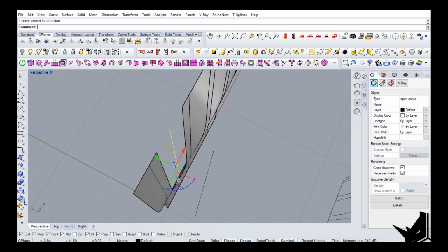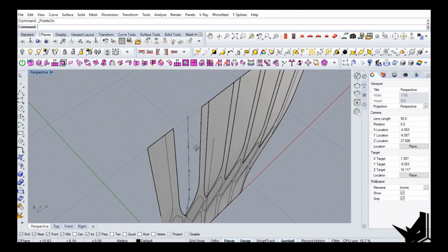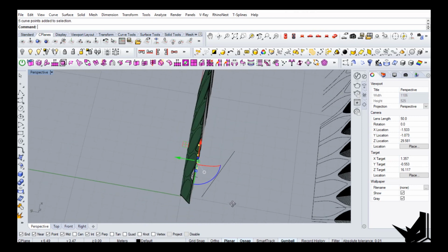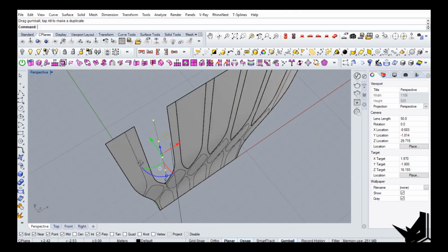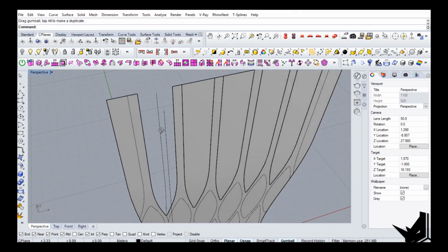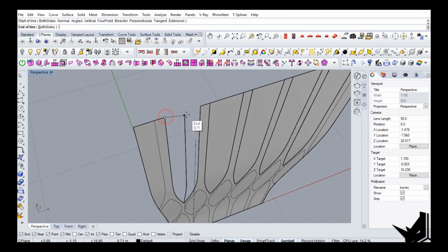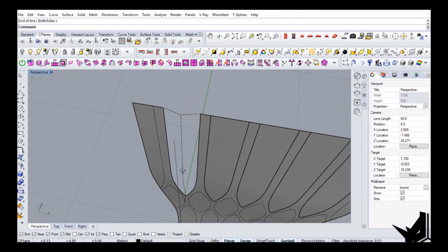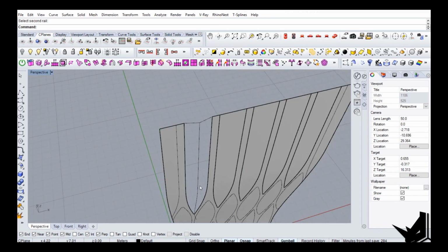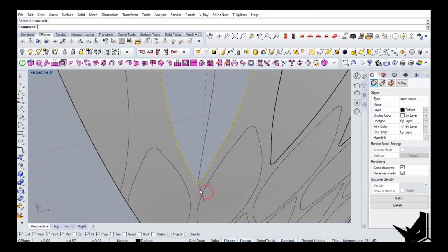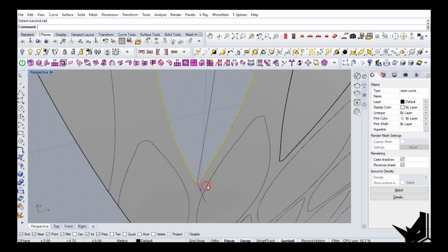and we're gonna say show me the control points. We're gonna select these guys here and move them a little bit outside, like so. Once we have this, then we're going to create these two parts here. So now the question is, how do we actually connect this surface? So in order to do this, we need to actually split first. We need to split this curve in half.